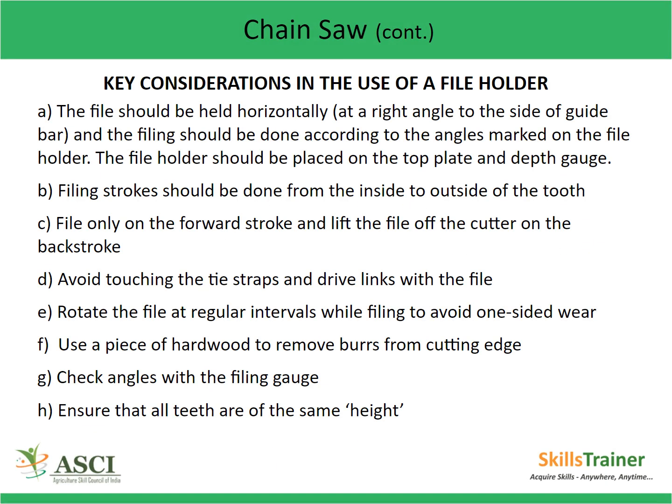Key considerations in the use of a file holder. The file should be held horizontally at a right angle to the side of the guide bar, and the filing should be done according to the angles marked on the file holder. The file holder should be placed on the top plate and depth gauge. Filing strokes should be done from the inside to outside of the tooth. File only on the forward stroke and lift the file off the cutter on the back stroke. Avoid touching the tie straps and drive links with the file.